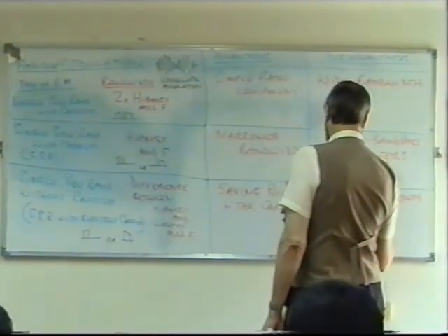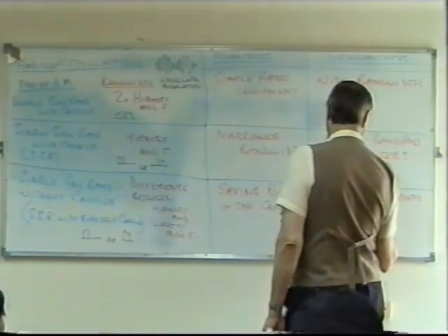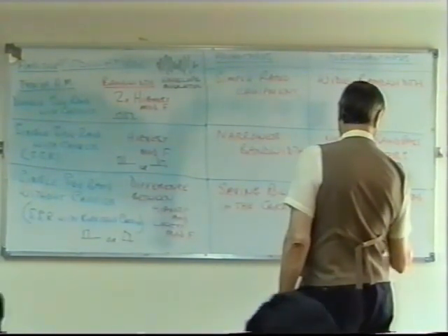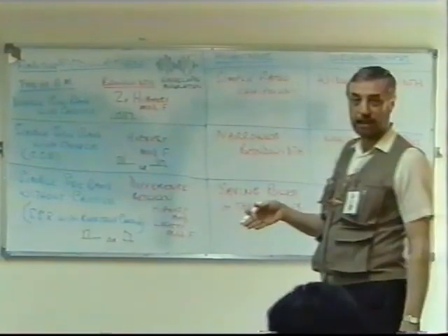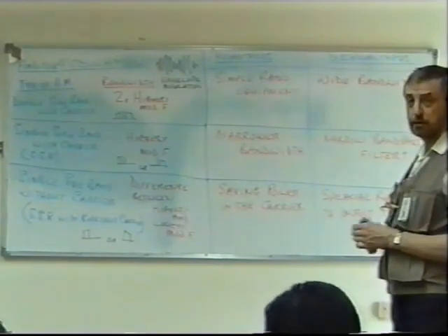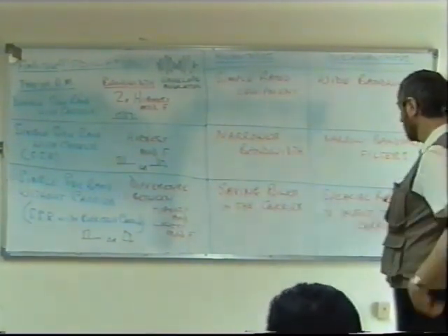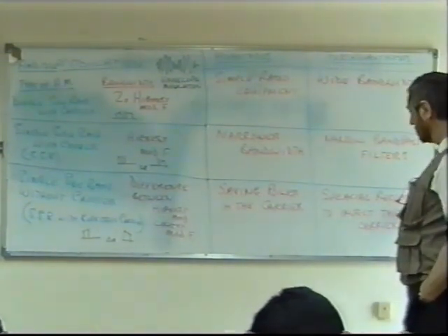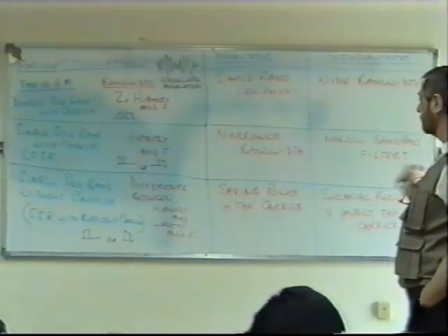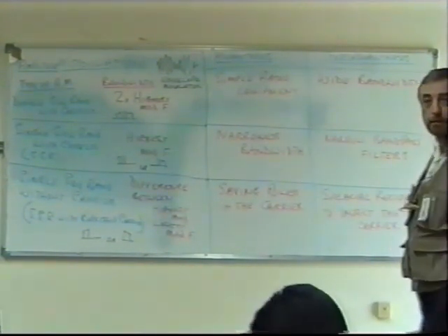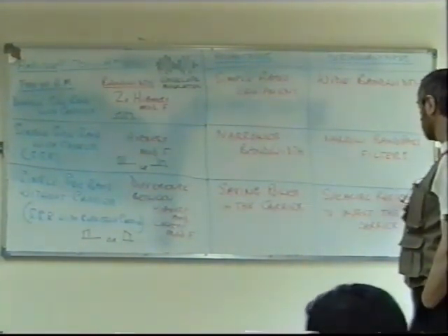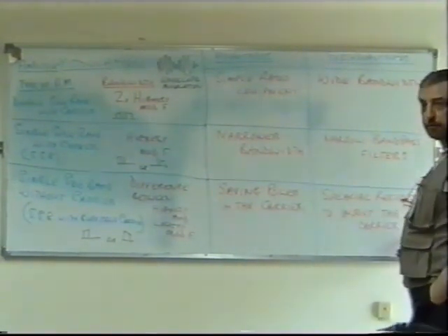To inject the carrier. Inject means to put back into place again what was missing, because like we said, you cannot really demodulate without a carrier. You've got no reference, and this is where it gets a bit difficult. But of course we have a big advantage: very efficient in power, narrow bandwidth, but a more complex receiver. Special receivers needed to inject the carrier.